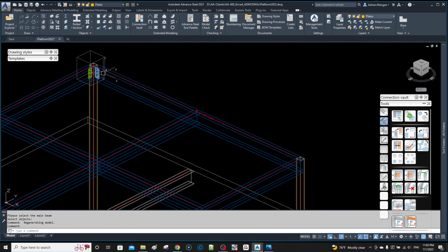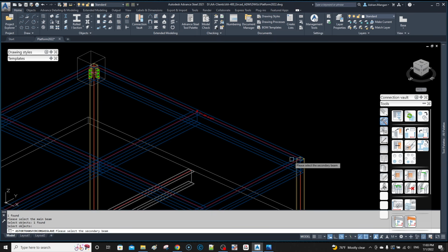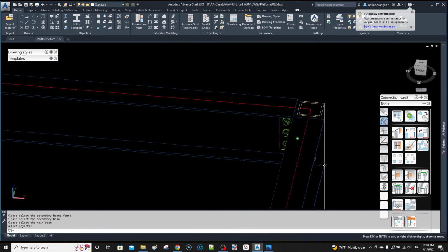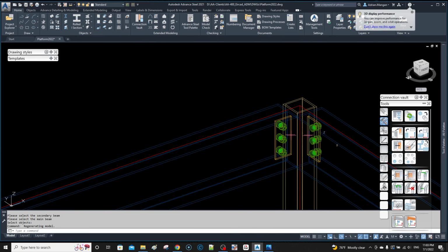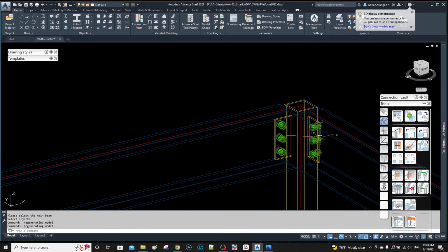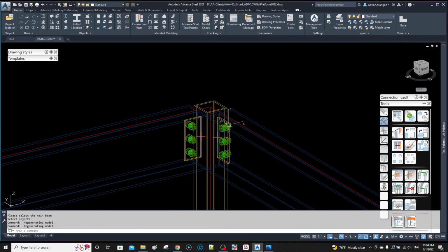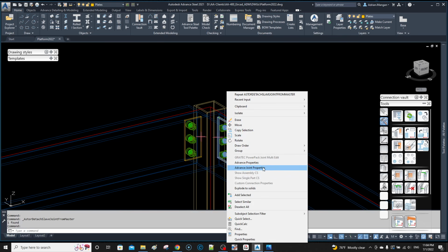Generally, if this plate's on the inside, I'll want this one on the outside, but we're going to have the same clash issue here on the corner, so that's fine. We can copy this one over. So let's copy them over and see what happens. So let's copy it over to here, and let's copy it here and see what happens. So now this one is good and this one is no good, because I want this one to come on from the outside also. So let's come in here, click on this, remove it from the joint group,